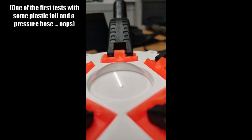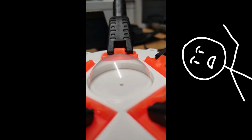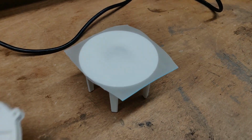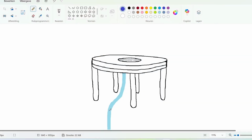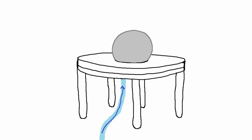For this, I used the bubble inflation test, and you might be asking, but why are you using a bubble inflation? What? Let me explain. A bubble inflation setup consists of an inflation platform, where a film of material is clamped between the platform and a circular rim at the top. Air is then supplied through the platform, which causes the film to inflate into a spherical shape, the bubble.